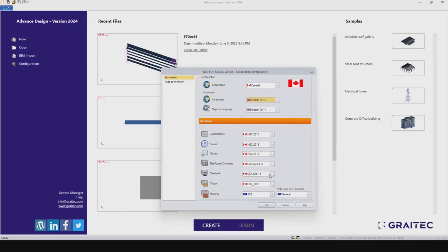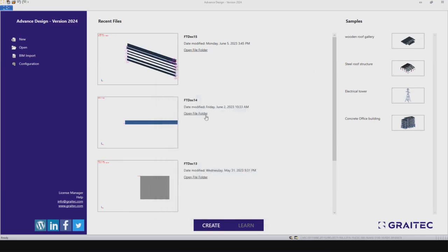And here in Steelwork, as you know, we have all of the codes, even past codes here, but the AISI S100 is accessible from here. Basically, you can select the code and the Steelwork will be done based on the AISI code for cold form sections from here. So I can use S16-19 AISI code and click OK.